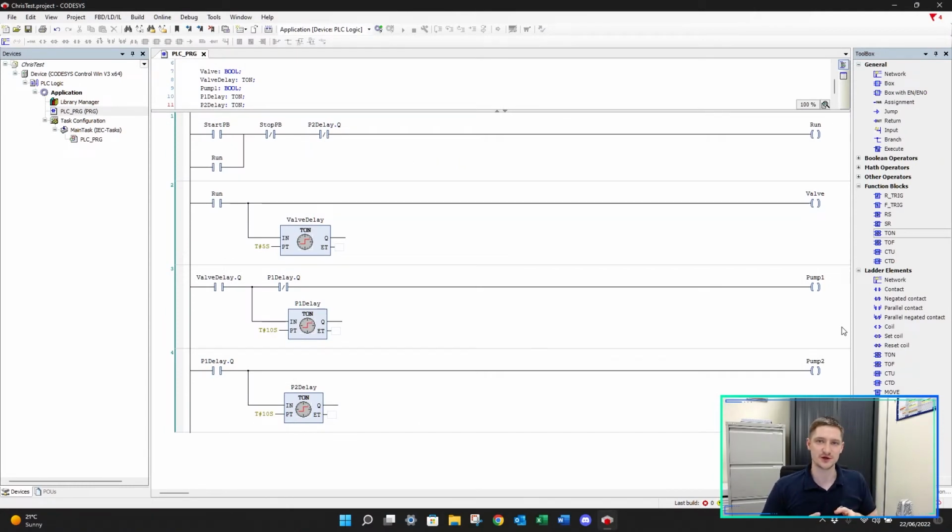On the previous video we looked at TOF timers. On the previous video to that we looked at TON timers. On this video here we're going to have a look at counters. Now I've got here our program that we completed for our TON timers, which was our valve and pump program. What we're going to have a look at now is we're going to modify this program to now do this within a couple of batches. So instead of just doing one cycle and then stopping, we'll have it do a couple of cycles and then stop after that.